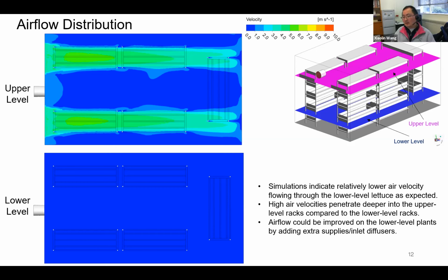The reason I ask is that if you use turbulent flow, it will definitely enhance the heat transfer. But at the same time, it may also enhance the mass transfer. When it affects the mass transfer, the vegetables may lose moisture, which may affect their quality after being stored for some time. You got my point, right? That's why I'm asking. Do you normally prefer laminar flow or turbulent flow? I think it's a balance between heat transfer and mass transfer. Is that correct?